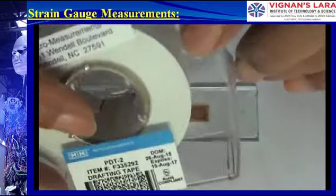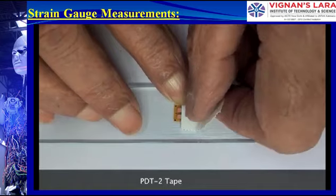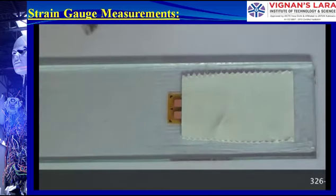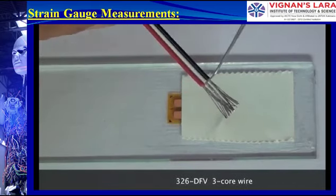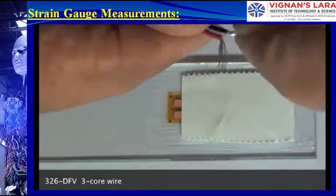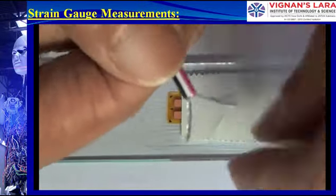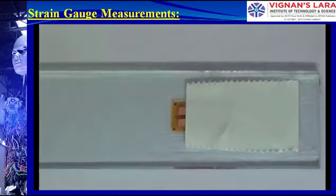The next step is to attach lead wires to the strain gauge. The gauge is covered with a piece of PDT-2 tape except for the tabs to protect the sensitive grid of the gauge during soldering. For single element strain gauges, a 3 lead wire connection is used to connect the gauge to an instrument as a quarter bridge. The conductors of one lead wire are separated from the other two, and the conductors are twisted tightly until the twist extends all the way to the insulation.